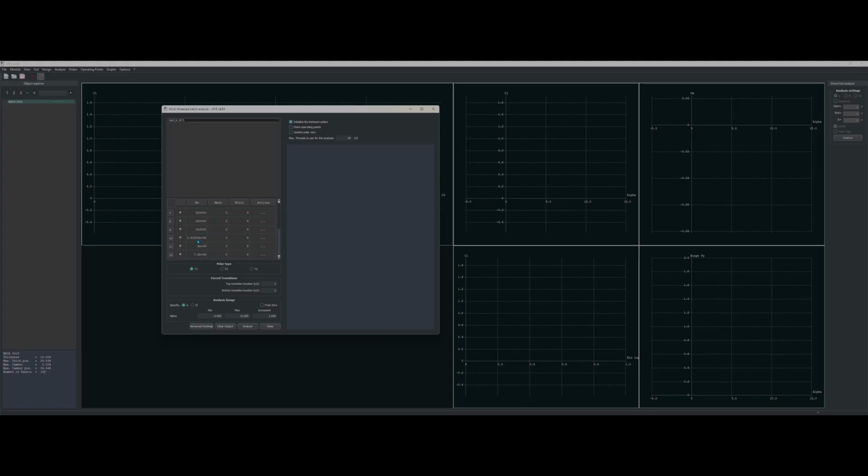And it's important that you have a Reynolds number that corresponds to the wing simulation. In this case, it would be this Reynolds number right here. This Reynolds number is what corresponds to the actual simulation. So if we were to calculate our Reynolds number of the airfoil, we would get this Reynolds number right here because our chord would be 1, and then of course we have our parameters. So yep, make sure you have that.